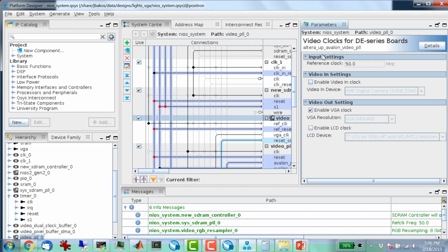The problem is that it only does the looping when you're in the usleep, which is a synchronous blocking function, right? So there's no way to use that information outside of that function. There's no way to track how many cycles have gone by inside your code. That's why we use the interval timer. But in the next lab, we're going to add another peripheral to the platform designer called a performance counter that'll actually just count cycles that we can access from the code.